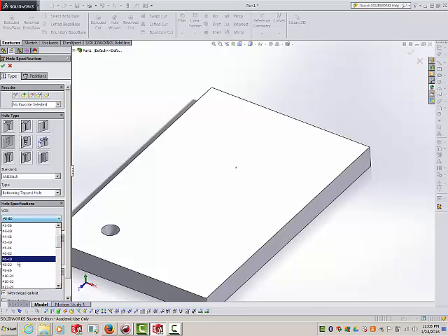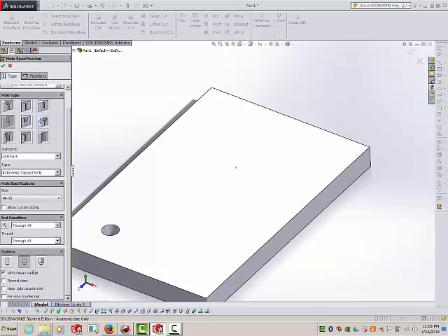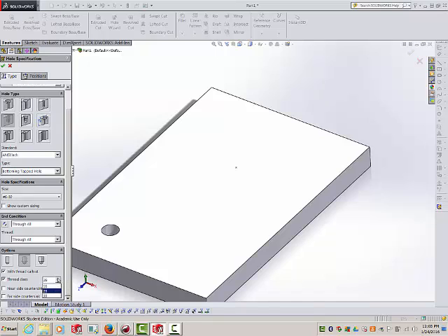So coming down, SolidWorks, the hole wizard has dialed in all of the data for making a correct 632 tap hole. So remember, we're doing a straight tap. And I have some options: thread callout, thread class. I could control that. I could add the countersinks in if I wanted to.